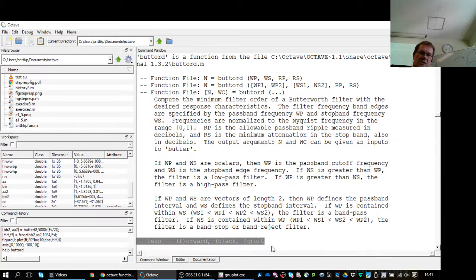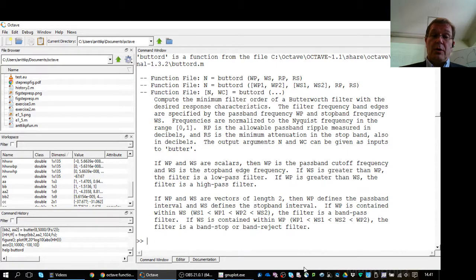So, design box. Let's try that one. Our order number, ON, that's not good. Or Orden is boot_ord. For example, now we have the 5 kilohertz again divided by Fs/2. Okay. Then the stop band start frequency we could put, for example, at 7 kilohertz, 7,000 divided by Fs/2.